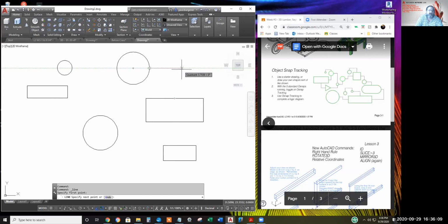Now check it out. When the two invisible straight edges line up, I get 2 polar tracking lines showing me to click next where those two polar tracking line-ish dotted lines appear. Lost it. There we go. Click. Now I can simply come straight down with an object snap, and there's nothing to trim, nothing to erase, nothing to fill in or nothing. Excuse me.